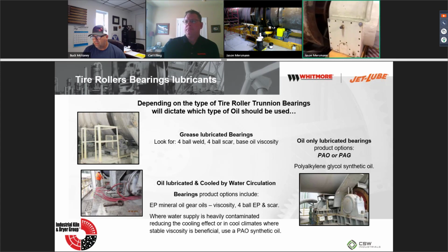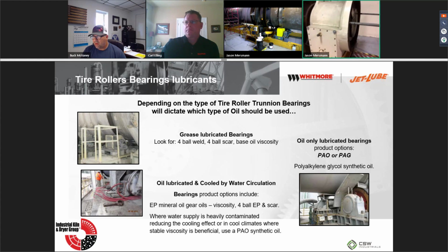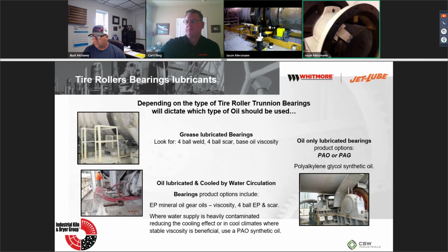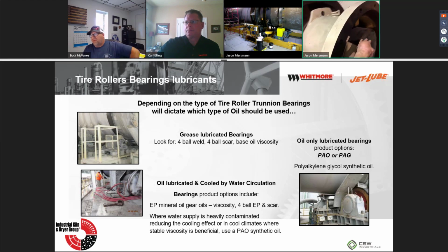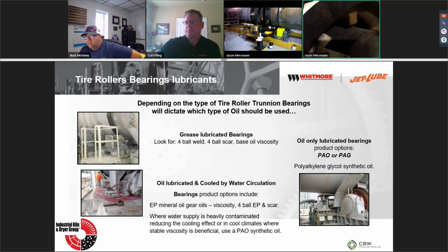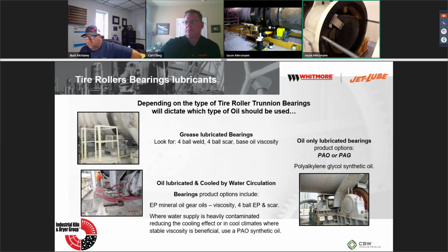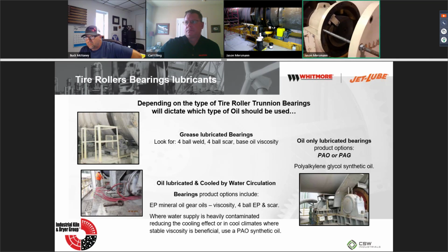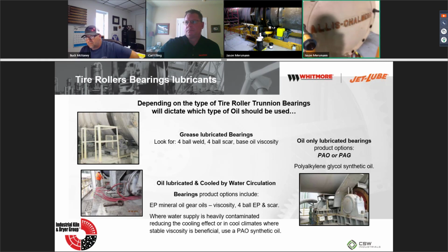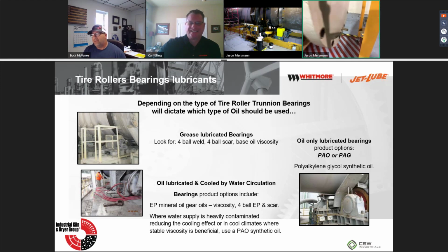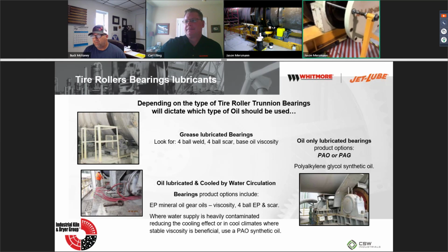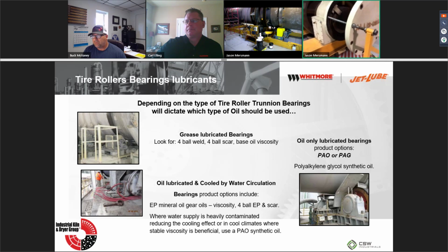So, as we were talking about, you'd have your water coming in and out. We go on the inside of the unit, and then you have your scoop right there, which would rotate down in, scoop it up, and pour it out, which would normally be a tray right here that we've pulled out for training purposes. It would dump on that tray, evenly disperse across that shaft, and help keep that lubricated. Carl will talk about this a little later, but as you can see on ours, for training purposes, we don't have anything on the drains. Making sure you have a good sight glass on there where you can take samples can really help you get the data you need to keep your unit in top running shape.